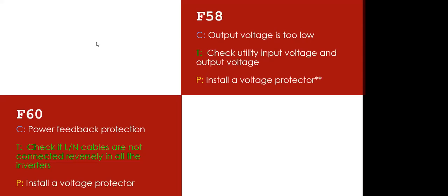F83. In this case, when we want to connect Genex inverters in parallel, we advise that all the batteries should be connected as one bank, and each inverter takes its source from that particular bank. So if you are using 8 batteries, you don't connect 4 for one inverter and 4 for another and then parallel the inverters. The inverters will be sensing different voltages, which is not good for inverters that are in parallel.